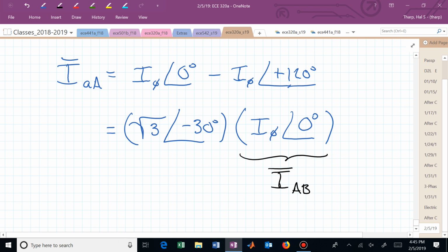What we want to be able to do next is calculate total power based on measured quantities. And what can we measure probably in the field? The line voltage from transmission line to transmission line and the line current, the current in the line. Can we now find power equations just using those two and maybe the angle of our impedance? That's where we will pick up next time.